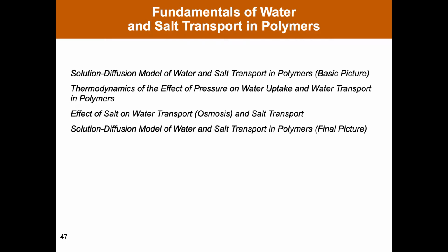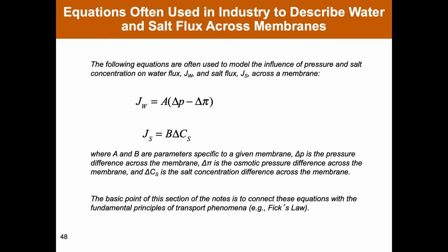So I'd like to talk about the fundamentals first of water and then later salt transport through these membranes. The way that you'll see the water and salt flux described in the literature is shown here. The water flux is taken to be proportional to the pressure difference across the membrane and also the osmotic pressure difference. That'll be the difference in salt concentration across the membrane.